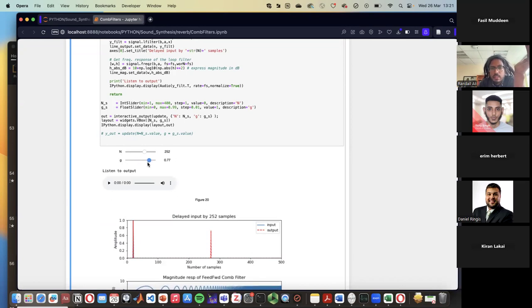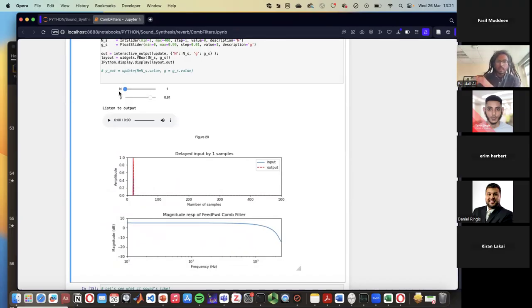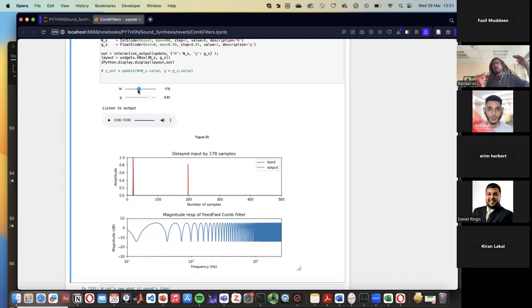And if I look at the frequency, the magnitude response from this filter, you see something really interesting, right? So if I don't have any delay, the magnitude response looks fairly flat. There's a bit of a roll off to the end. But as I increase this delay, you see sort of a comb-like filtering effect. What's going on is that the main sound that travels from path A to B is interacting with that reflected sound, and you're having this sort of constructive and destructive interference. So that's why you have these valleys and these dips over and over.